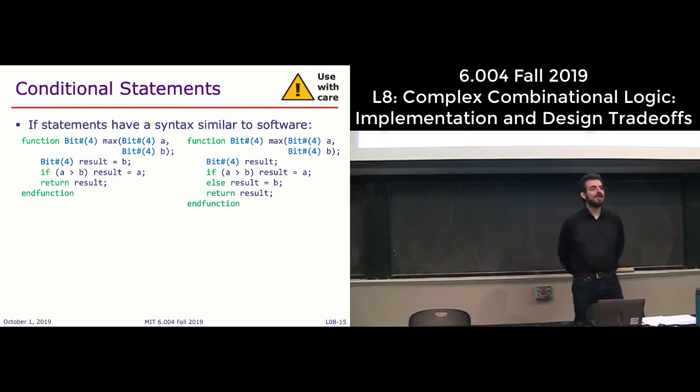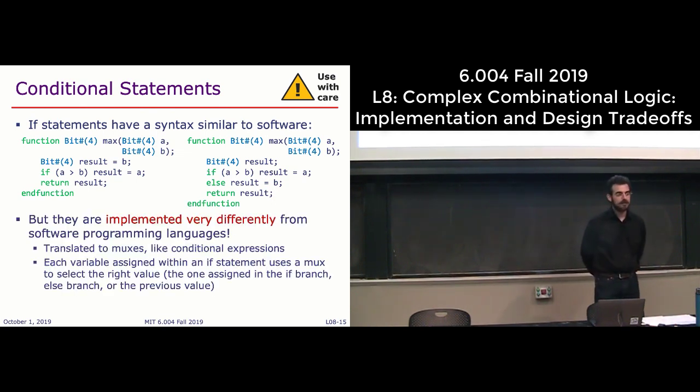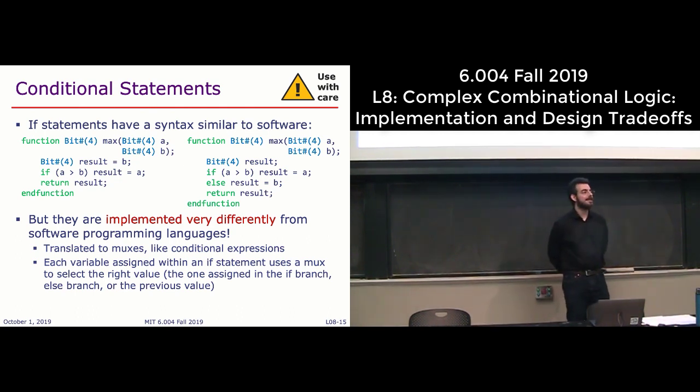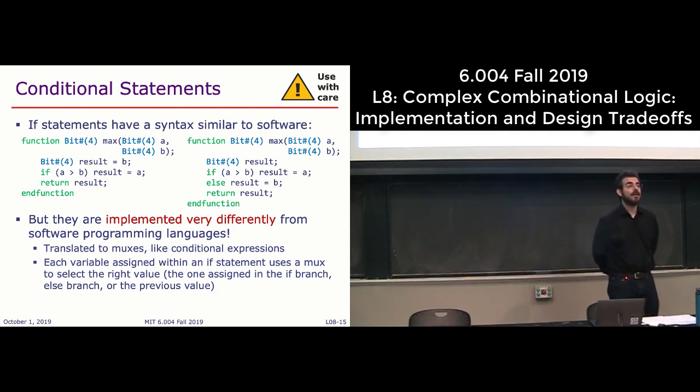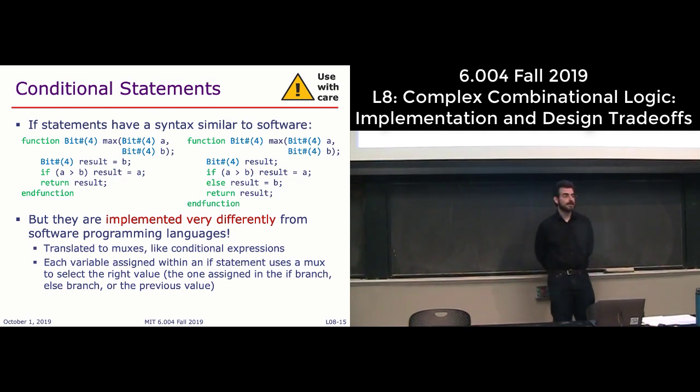Just like for loops are nothing like for loops in software, if statements and if-else statements are implemented very differently. This is just a fancy way to have conditional expressions. So they're translated to multiplexers. They're just expressing multiplexers.